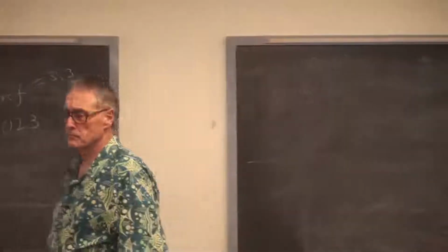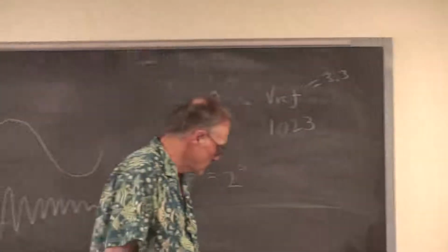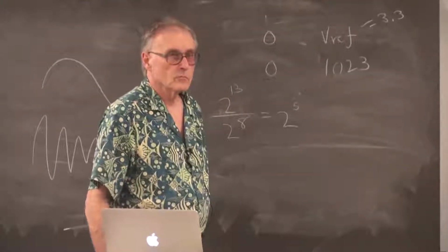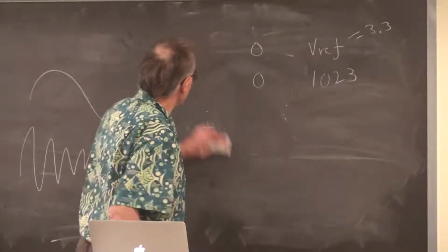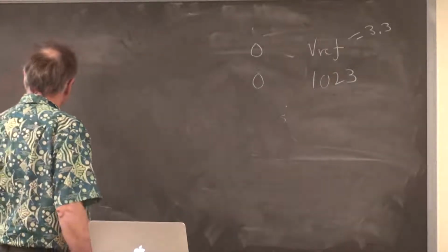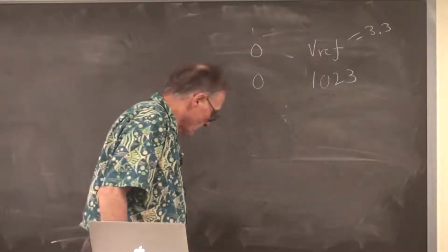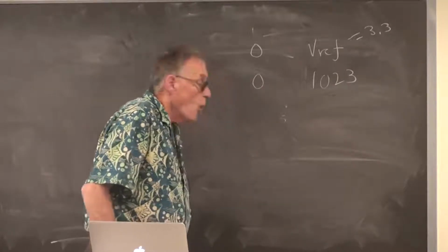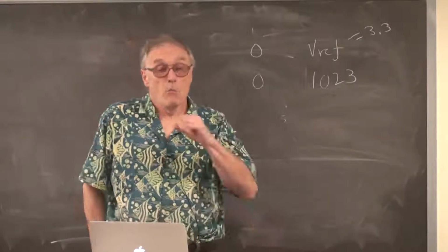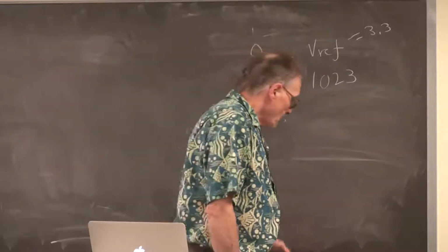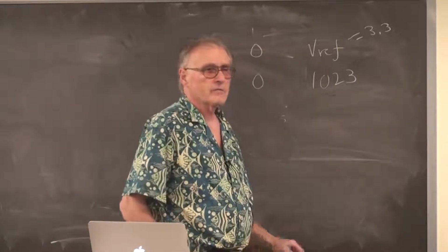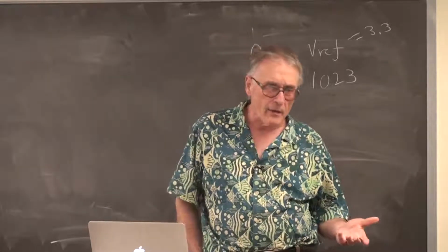Question? So the output from an ADC can be anywhere from 0 to 1023, like 10 bits. For something like sound, would that be high enough resolution? That's an interesting question. 10 bits is not really what you call high fidelity sound.